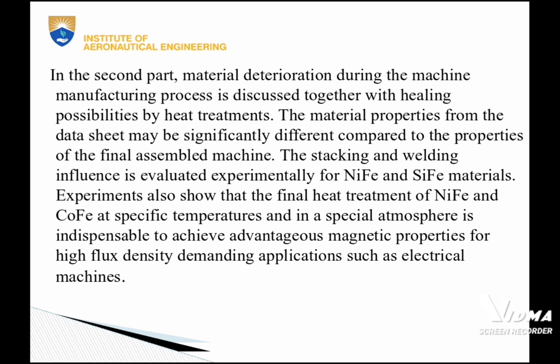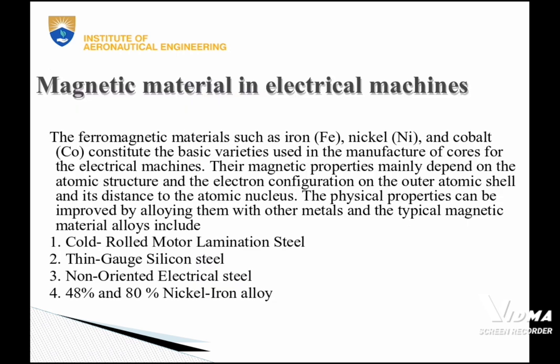Experiments also show that the final heat treatment of NiFe and CoFe at specific temperatures and in a specific atmosphere is indispensable to achieving adequate magnetic properties for high flux density demanding applications such as electrical machines.